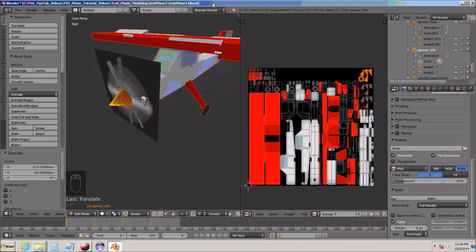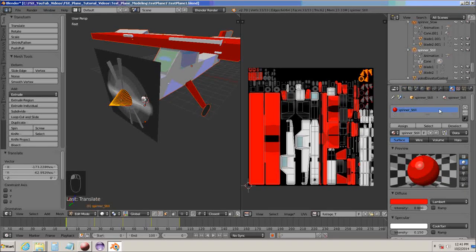Okay, so once it is done, your texture map will look something like this. Now remember, we just put in simple materials. That's where it got this all from. Even though you saw that the plane was completely black, that was just pulling off of the UV because we had it in a UV mode, and was showing that for the UV mapping at the time we had only black. But when it does the baking, it is pulling from the materials that we had for the different items. And remember, we have a lot of different materials for the body. So that's where it got all these colors from.